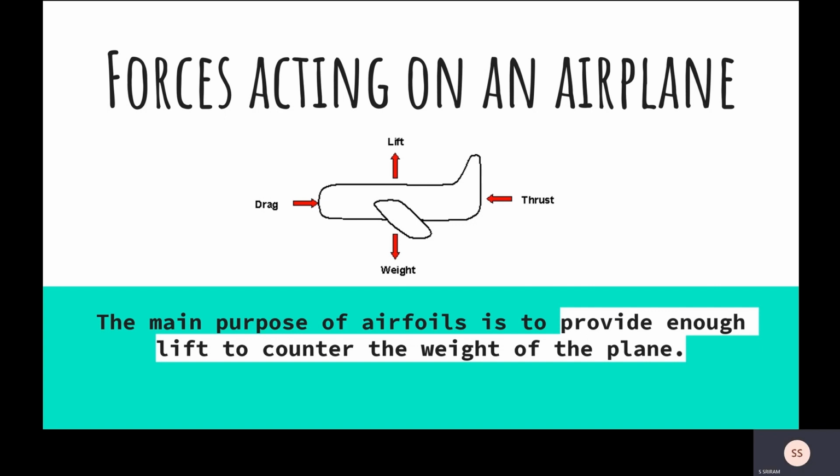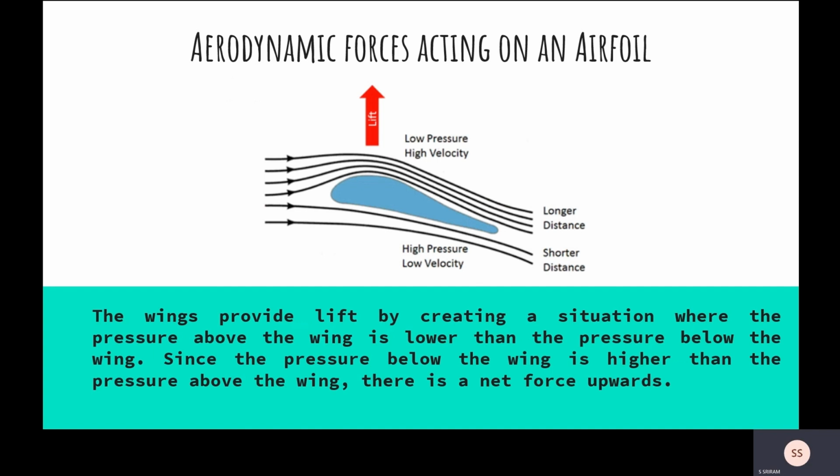Since we are working on an airfoil, let's understand what the forces acting on an airplane are. An airplane experiences lift, drag, thrust, and weight. The main purpose of airfoils is to provide enough lift to counter the weight of the plane. That is, you need to increase lift and reduce drag in order to obtain the optimum condition that will counter the weight of the airplane so that it can fly.